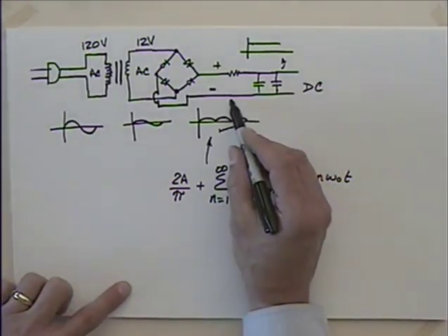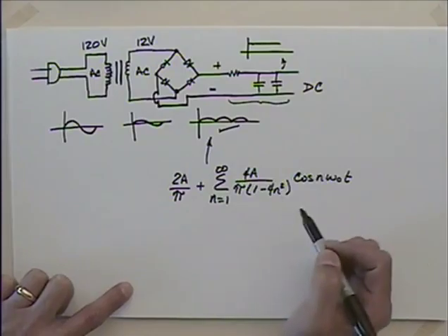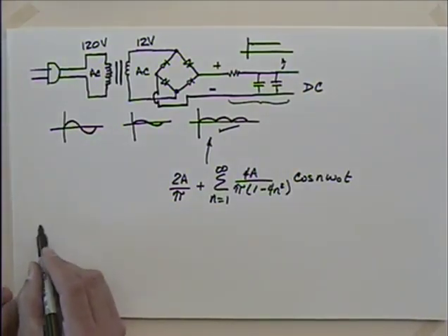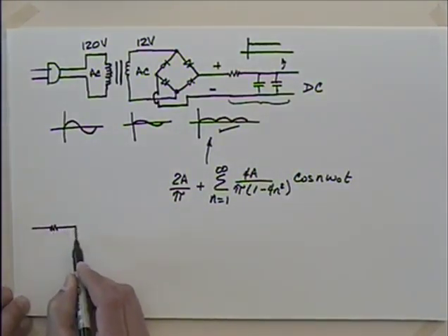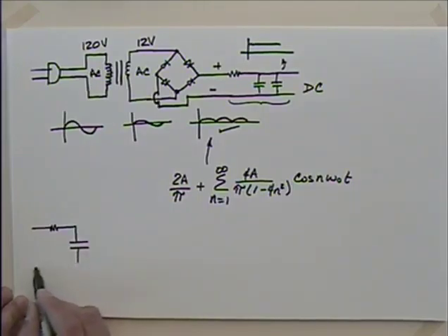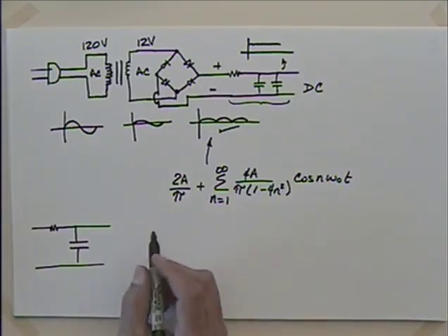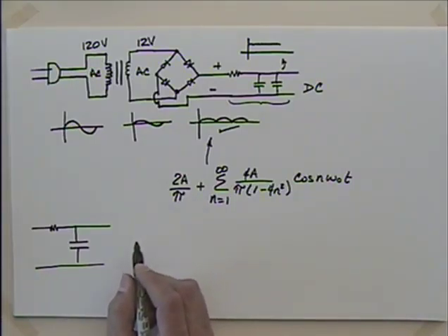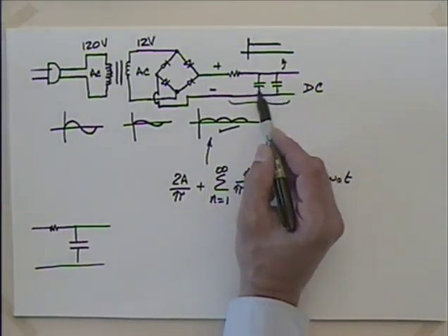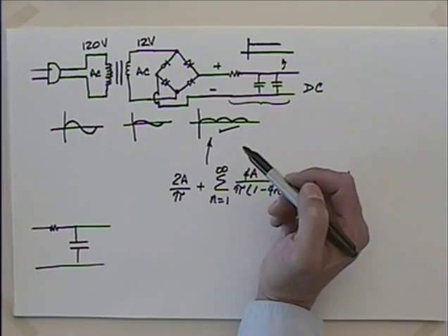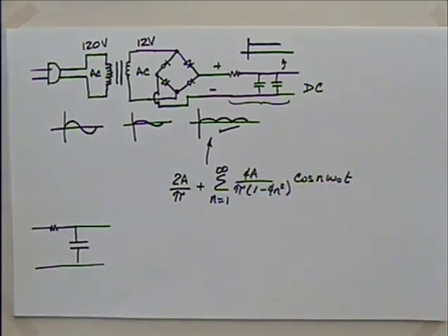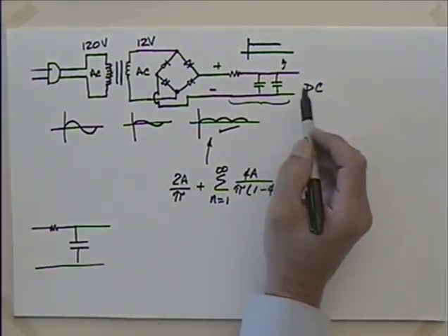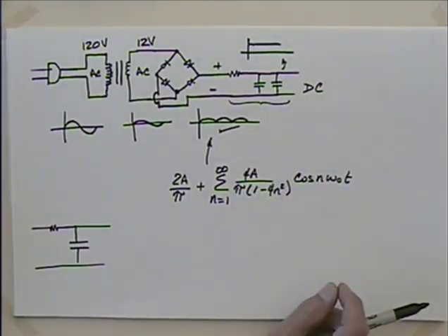And then we really have kind of a circuit here. So if I come down and look at that as a resistance and a capacitance, I could combine those two capacitors. A lot of times we put multiple capacitors in parallel like that, because that would increase the values, right? If I put resistors in parallel, it decreases the values. When I put capacitors in parallel, it increases the value, right? If you've ever done any MIG welding or whatnot, a good MIG welder, the whole bottom of it's basically capacitors, trying to smooth out the AC that's coming in.